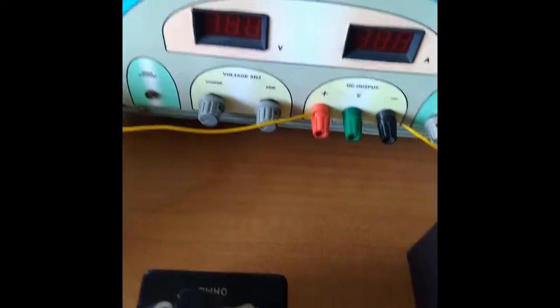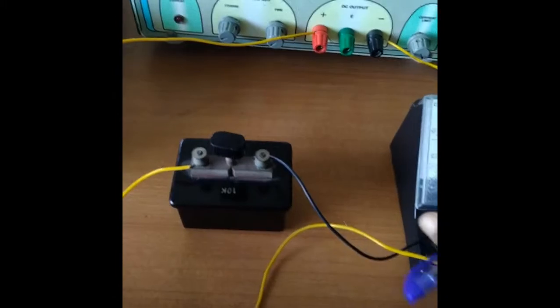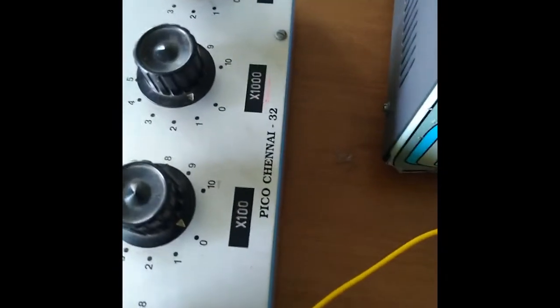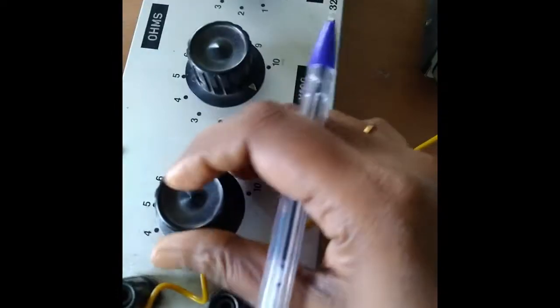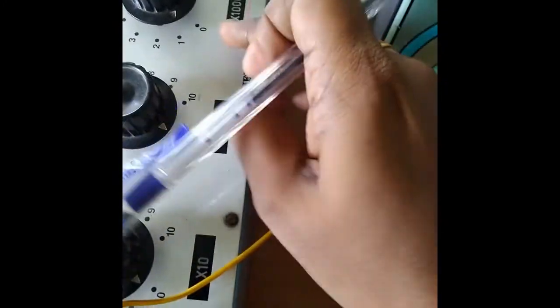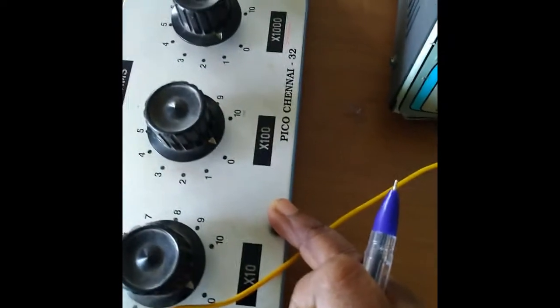Let us see what is the apparatus required for doing this experiment. So this is our battery, and we want to have 4 resistances. This is the resistance P and this is the resistance Q. Both the resistances P and Q were kept at known equal values, that is 1000. See here, this is into 10. If we put 2 over here, it represents 20 ohms. If I keep it as 0, it represents 0. And here into 1000, I have kept it as 1. So this resistance box gives you a resistance of 1000 ohms.